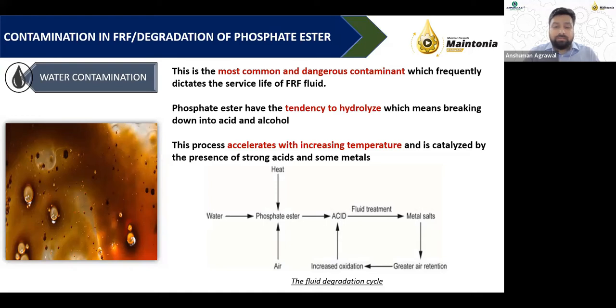More than that, it would spoil the resistivity, the fluid lubrication properties, and the functioning of the control system valves. The control system valves' operation and efficiency depend largely on how the phosphate ester, the control fluid, is performing.